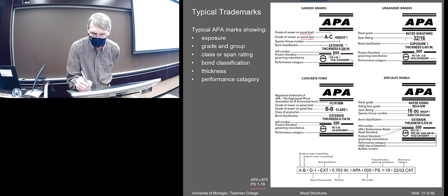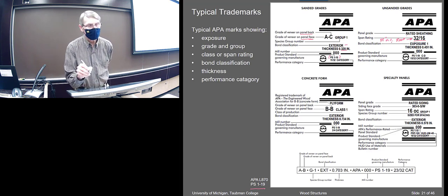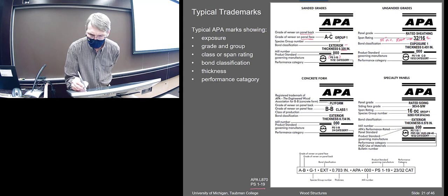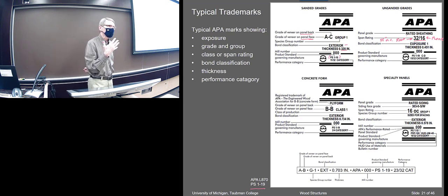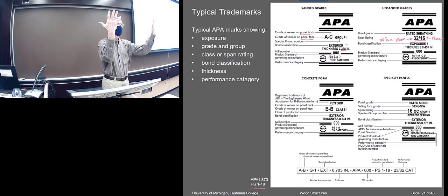So this is roof on center spacing. That's 32 inches on center spacing for the joists. And the other is for floor. I guess they figure a roof must be about 20 PSF, right? A floor, residential, maybe they think 50.